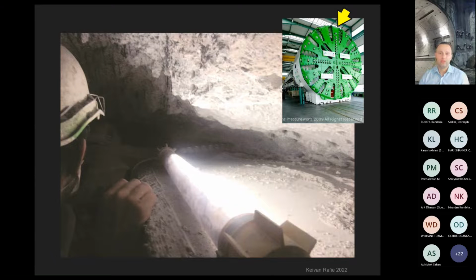So the friction after the top of the TBM hit the roof of the cavern is what stopped the TBM. Usually in typical projects, if you have a full face and you have all your rams, that would not have been a large enough friction to stop the TBM. But in this case, because we only had the bottom rams, the more we pushed, the more the TBM tended to go up and actually get more stuck in that area.